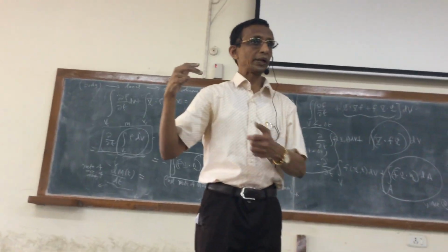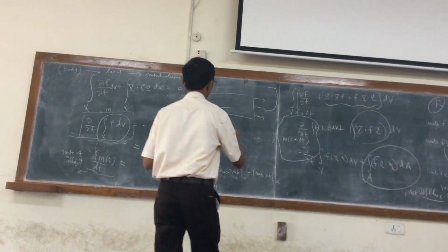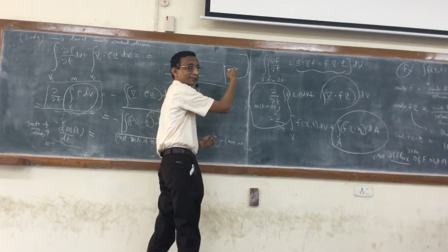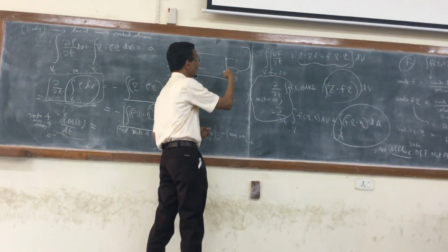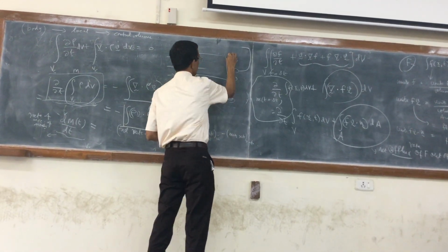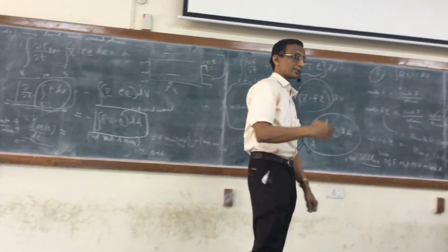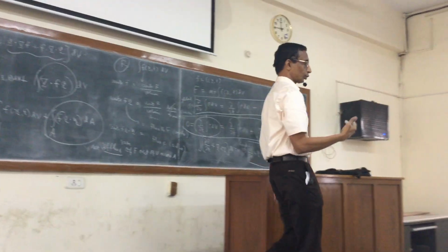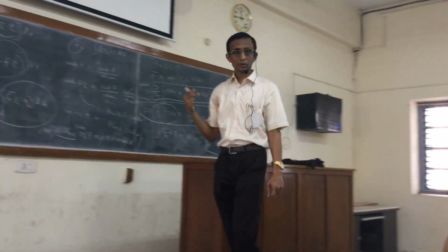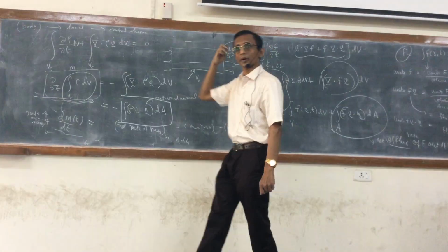So when you calculate rho v dot n, we get the mass flux out of a particular location on the control volume, let's say, on the control surface, where it is exiting or incoming. And then you look at the outward normal. So rho v dot n, that is only at one point. Because mass flux, even though it has a vector rho times v, mass is effectively a scalar. So to get a scalar, what I do is I take the dot product with the outward normal.